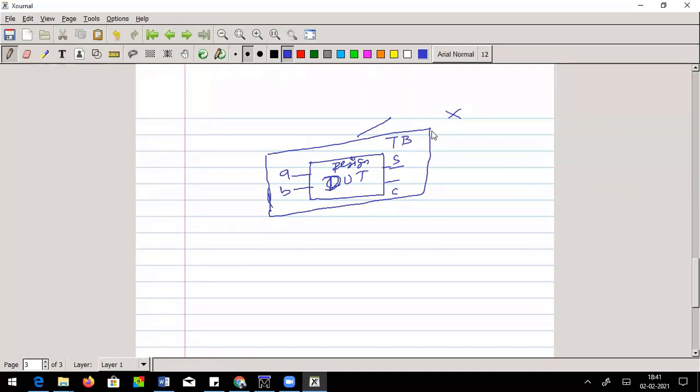That's why we say in a test bench, you can write all the constructs which are not synthesizable, right? Whereas those constructs, the commands which are written in the test bench which are non-synthesizable, should not be used in the design. If you do so, the design will have a problem, because the design needs to be synthesized, whereas the test bench need not be synthesized, or it will not be synthesized.